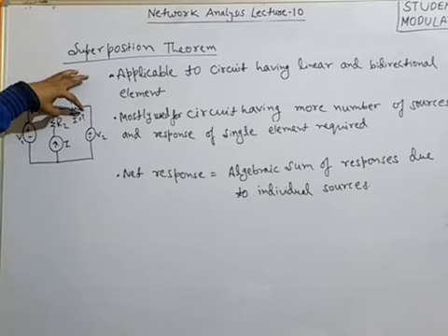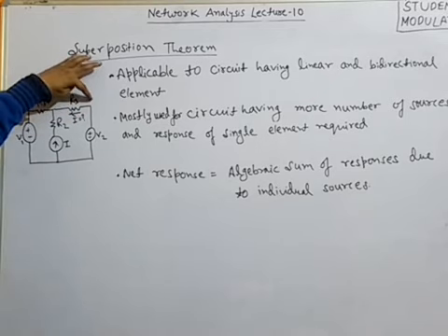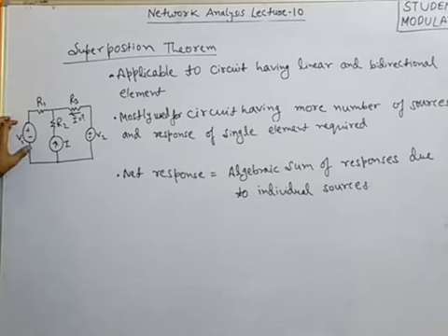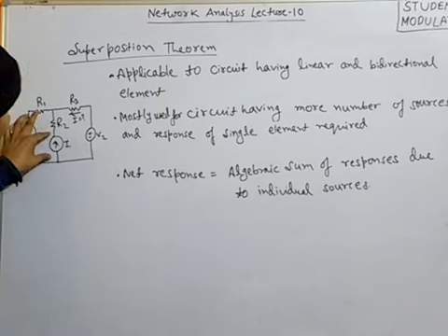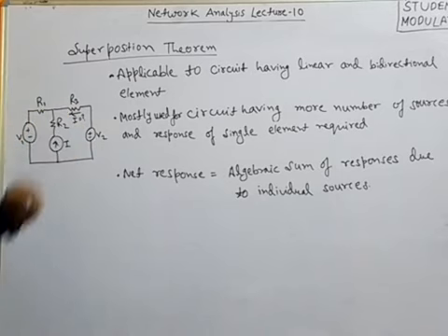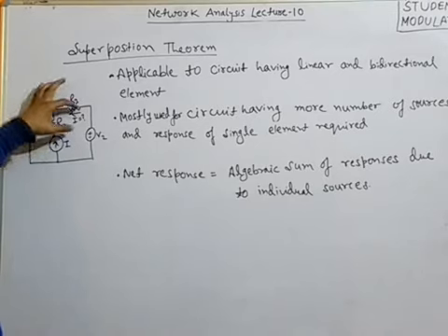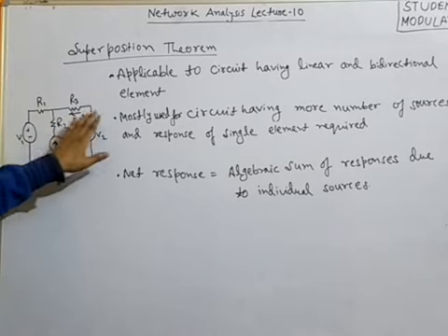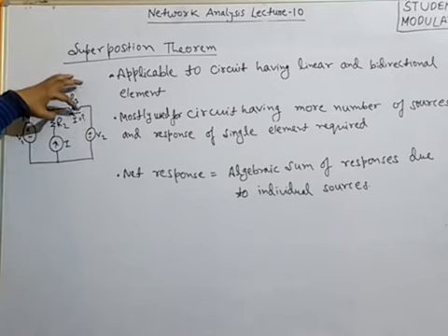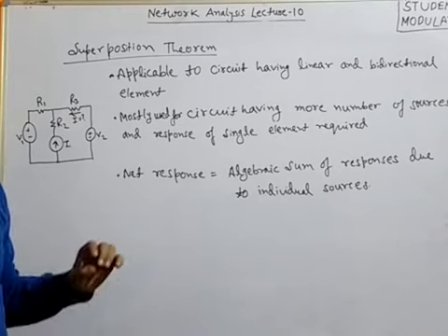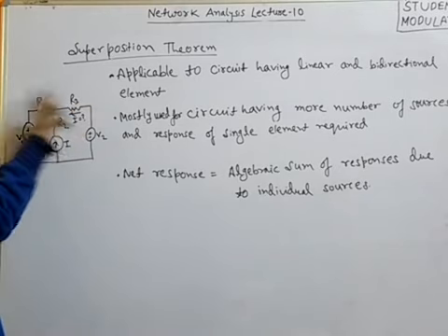To get the net response, that is, the net current through R3, we will put only one individual source at a time. We will first take V1, then the current I, and then finally V2. Whatever the responses due to V1 individually, I individually and V2 individually, we will sum them all, and the total sum will be the net current through R3.